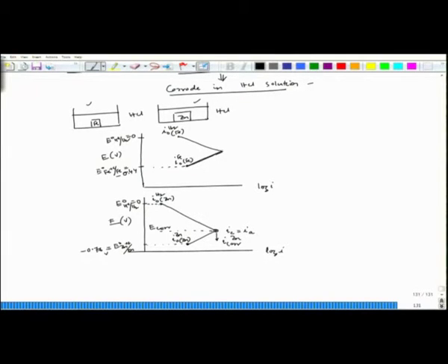So, in this case, this is the point of I corr, this is E corr, and here we have IC equal to IA. At this point we have no net current, but the iron corrodes at a rate of IA, which is equal to I corr.